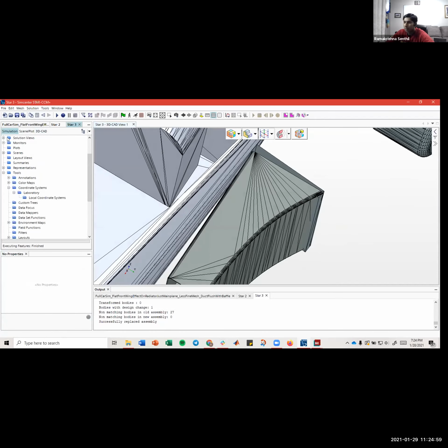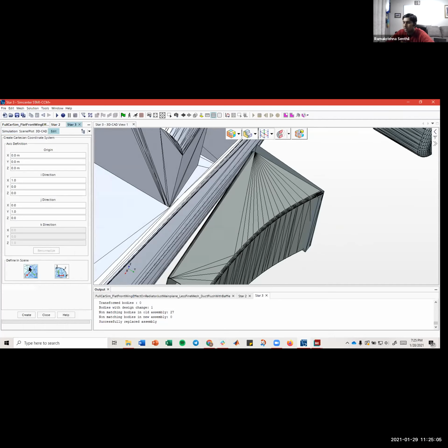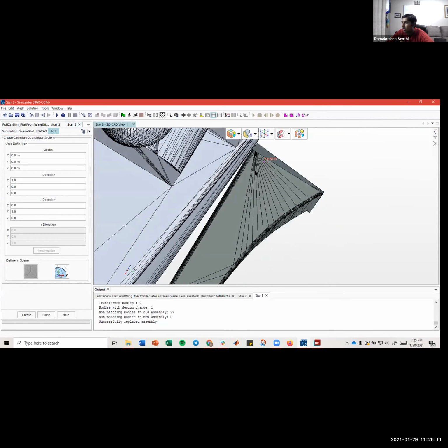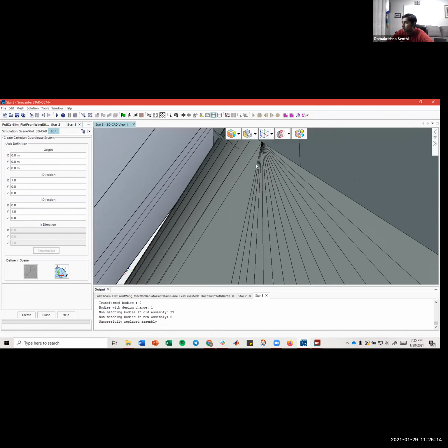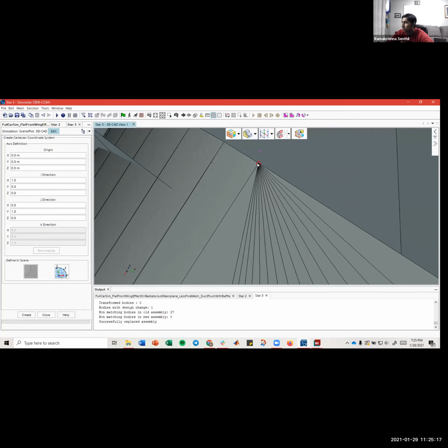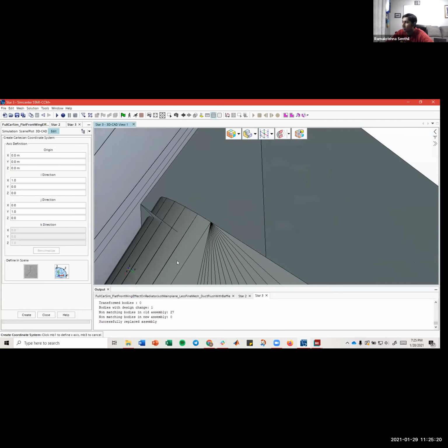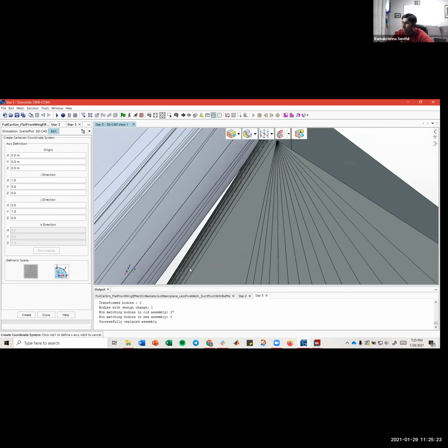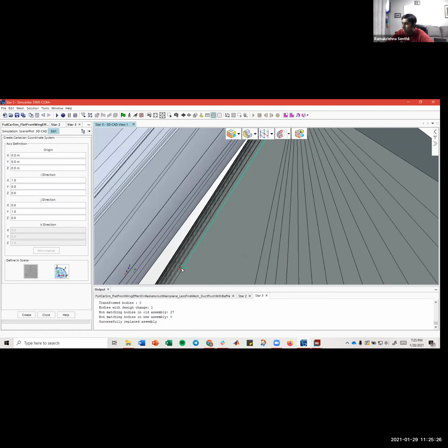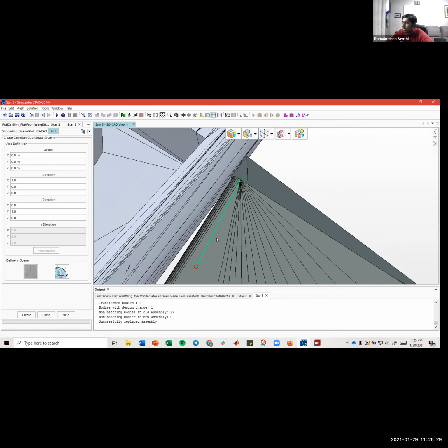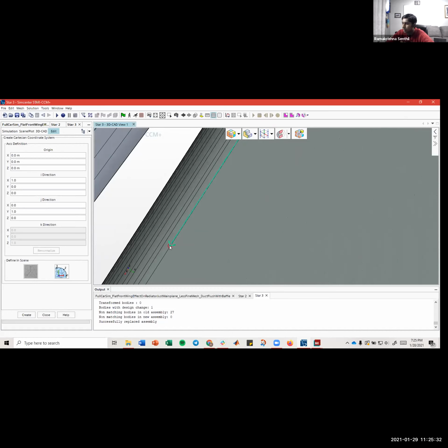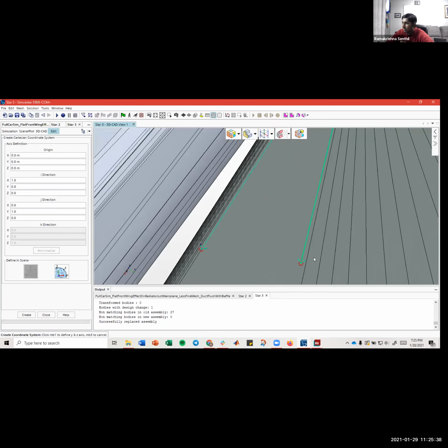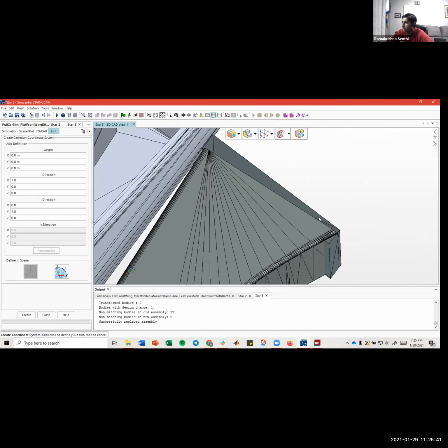Okay, so back to the coordinate system. Right click the local coordinate system, Cartesian, click that left bottom option right here where we can select 3 points. From there, essentially, we just want to select the origin. We'll say that this is our origin point, so you just click right here. And then we want to follow the x-axis, so just follow that line that's showing up, and try to align it as best as you can. So that's our x-axis, and then just click once you got that.